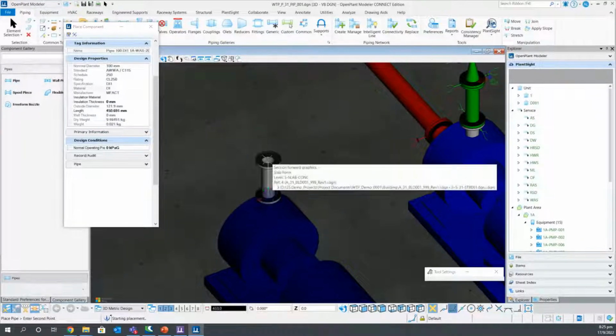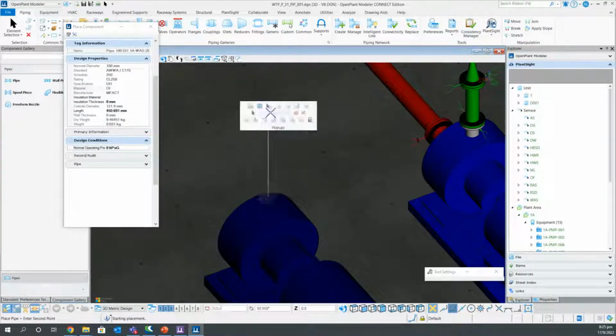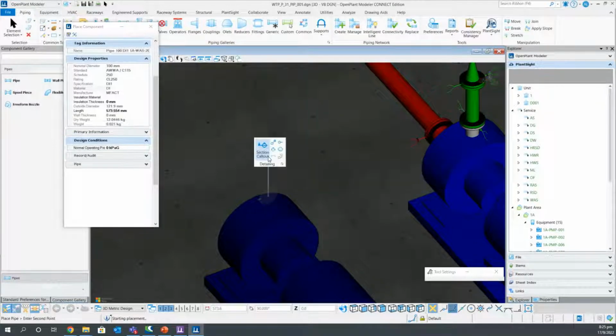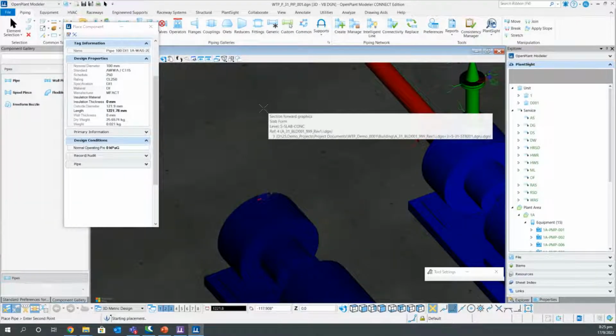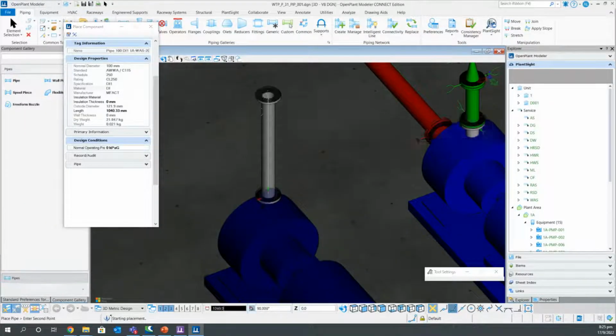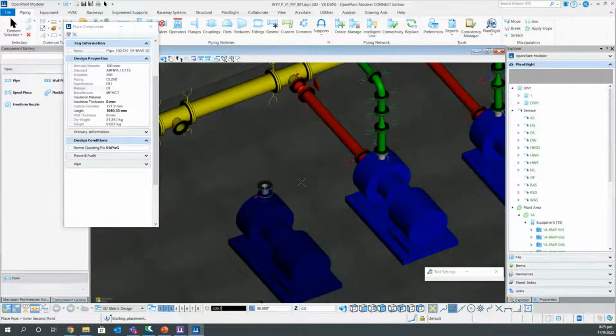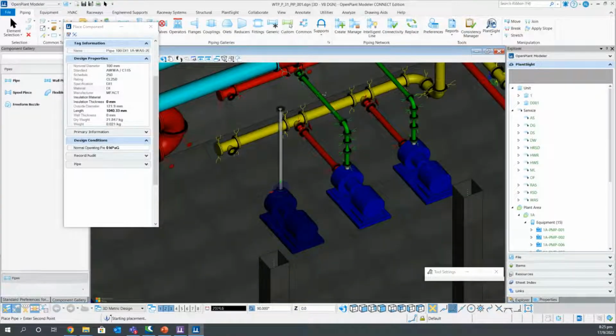And use the MicroStation AccuDraw now. Press T and F, and now orient it upward, and now snap it into the same height of this pipe.